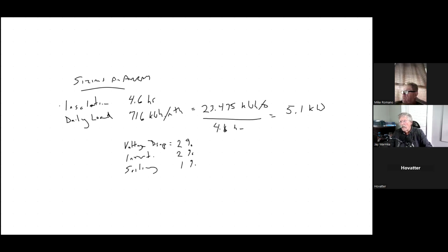So I'm going through the derate process. If I'm using a string inverter, because it uses the lowest common denominator, it's going to say, okay, if it's plus or minus 3%, like one of my panels generates 3% more, the other generates 3% less, you use the lowest common, so it's going to be a loss of 3% with a string inverter. But with microinverters, power optimizers, they tend to average that out because every panel operates independently of every other panel. So you can tend to ignore that. Let's say there are connections. So let's throw another 1% in for connections. And so now we're up to 6% loss.